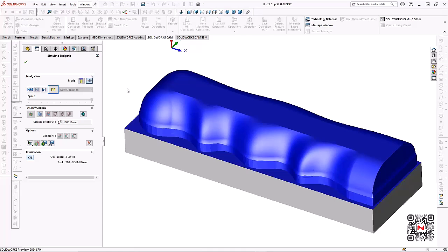I'm going to do the machining. You can see I went about halfway down on this part. We would likely flip this over, put it in some soft jaws, and then do a very similar process to the other side of the part in order to finish this part.